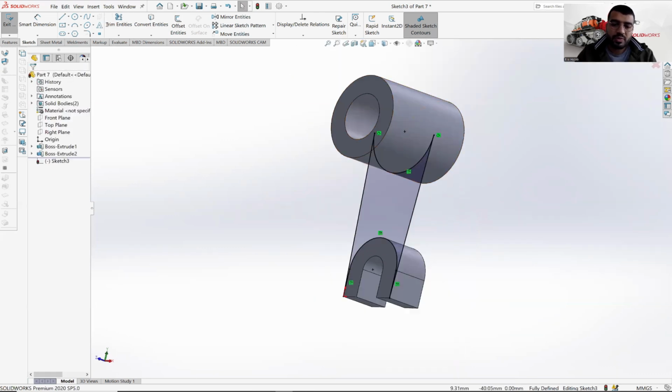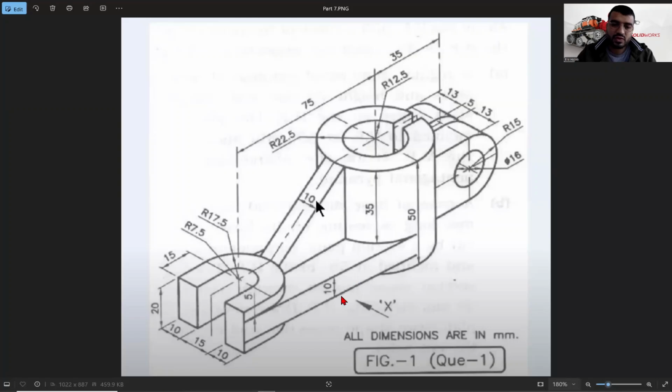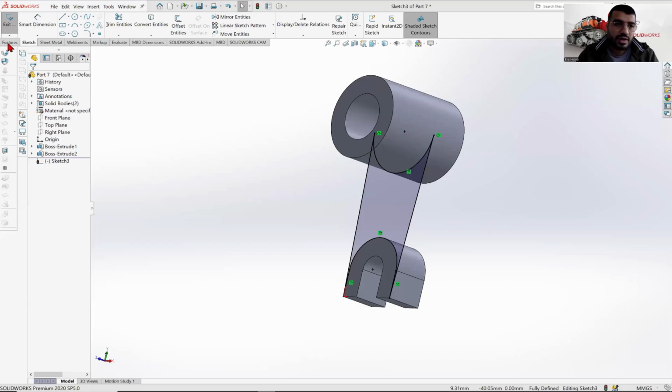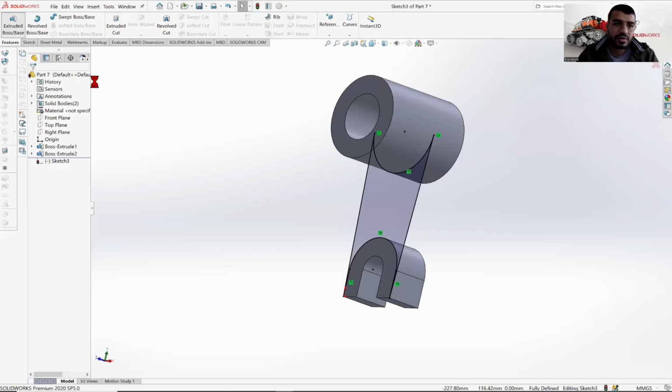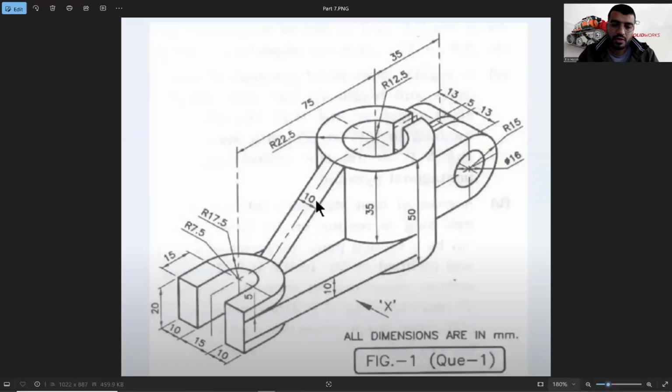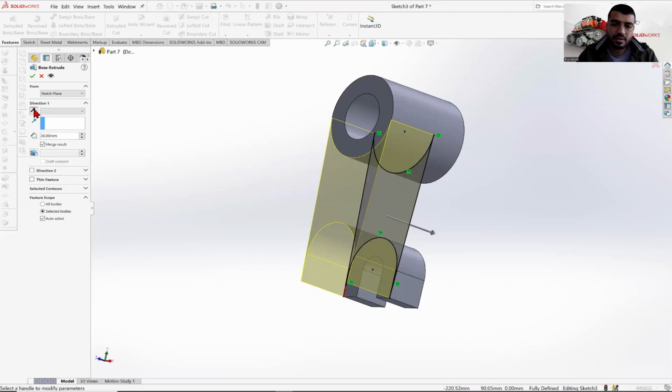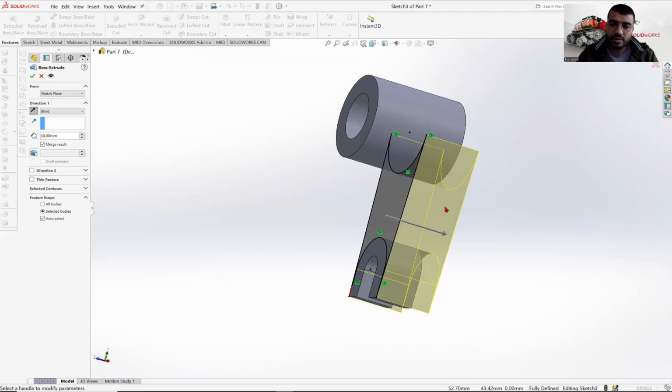But now my main objective is to do an extrude of 10 millimeter of height, by doing also another step, the 5 millimeter offset from this upper surface. So let's first do the first step. So here it's 10 millimeter, extrude bottom 10 millimeter. I choose it instead of 30, I choose 10, enter. Then